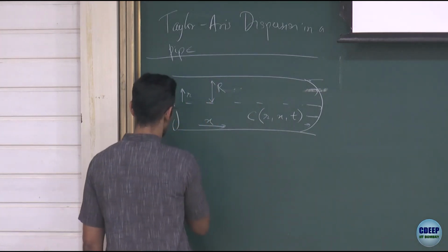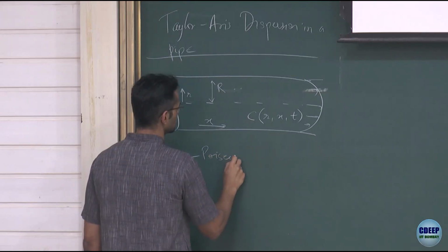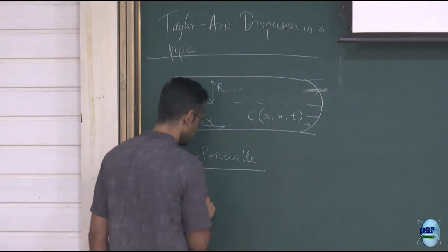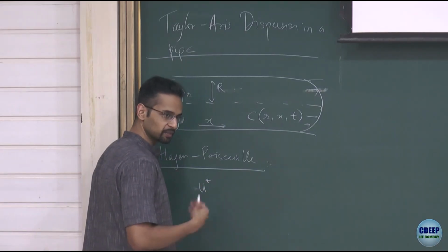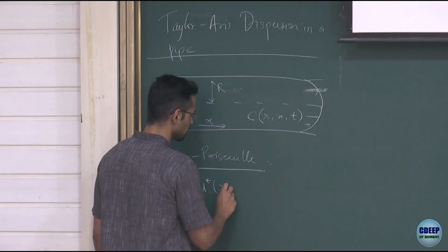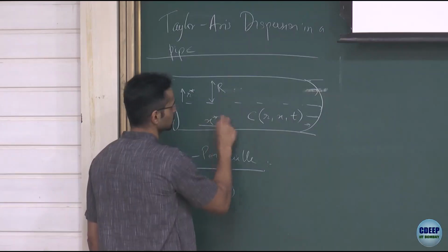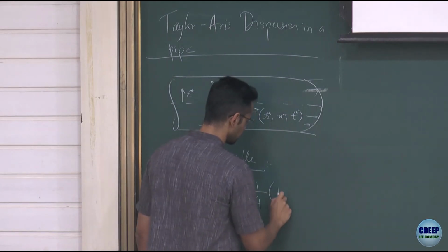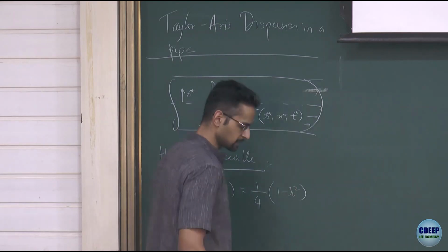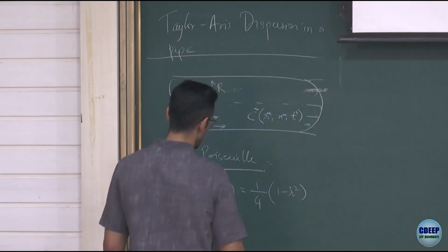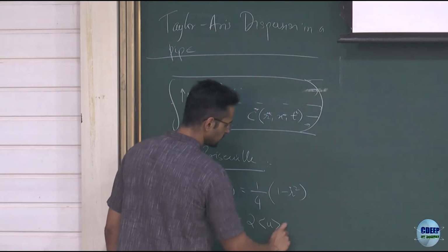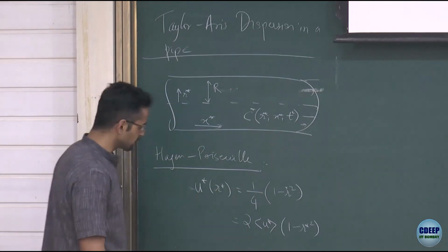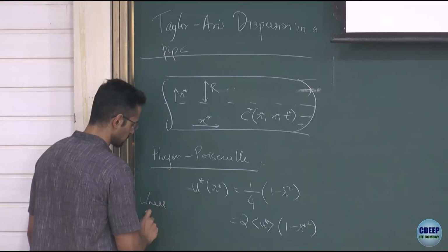Okay, which I'm sure you know how to derive. Right, from the Navier-Stokes, if we take fully developed unidirectional assumptions, you can get the velocity profile. I'm putting a star to denote dimensional quantities, which I will later non-dimensionalize. So u is only a function of the r direction. And one can easily show that it has the following relation. And this in turn you can write as twice the average velocity, times 1 minus r square. Okay. Where the average velocity, so this is the cross section average.